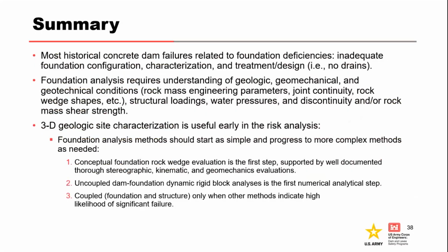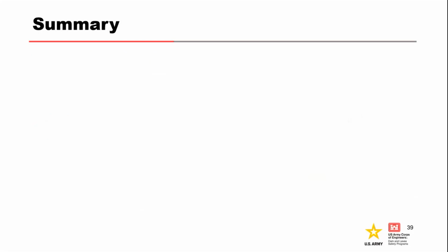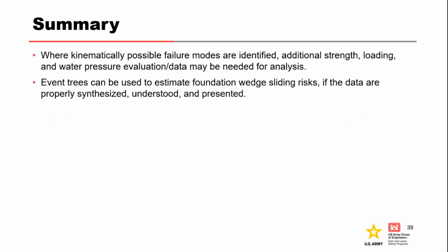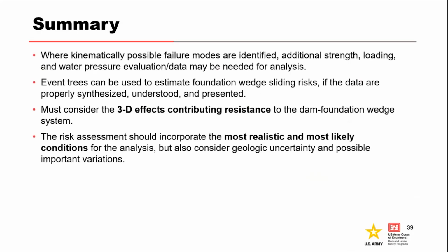Most historical concrete dam failures are related to foundation deficiencies. Foundation analysis requires understanding of the geologic properties in the foundation. 3D geologic site characterization is useful early in the risk analysis and should gradually be increased as more information is needed. And then I'll just highlight the importance of considering 3D effects contributing to the resistance of a foundation wedge system.